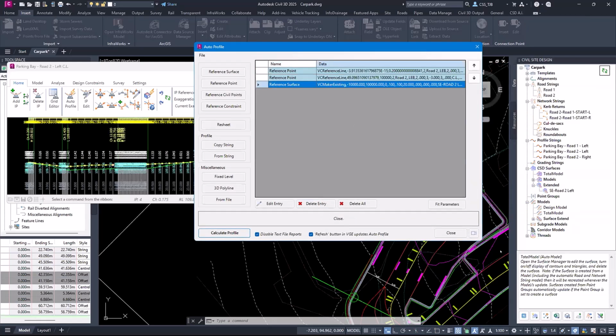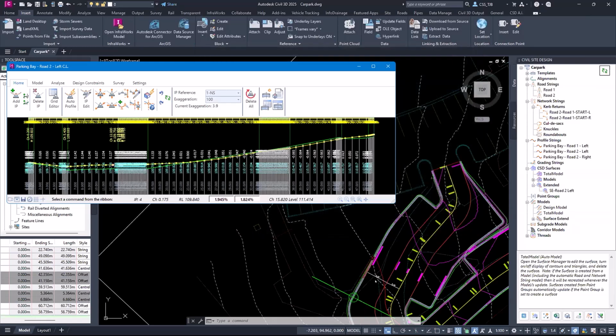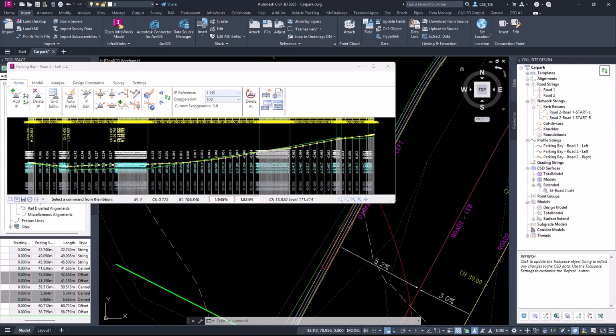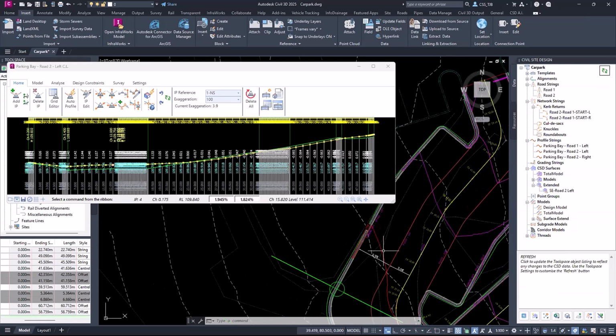And then I calculate that and I close out of that. And then I look down here and I go, oh, the labels haven't changed. And then I just come up and I refresh my models and all my labels update. And you can see there I didn't draw that completely perpendicular, but that grade is now 3% running parallel to that. And you can tell by the contours. Yeah, that's a nice smooth contour shooting off the side.